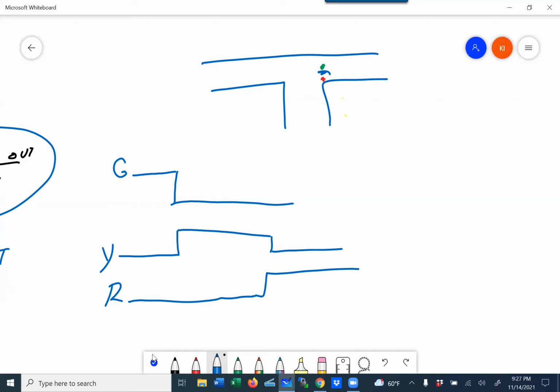So for each one of the lights, for each lane, when you're building the line, remember, earlier, you had a circuit in lab 3 or whatever, where it gives you the priority, and then you would have 3 lines coming on. You would have a green, you will have a west green, a south green, and an east green, basically lights that would start to come up, okay? So now you can't use that because in your previous case, when green went away, red immediately came on. You can't do that anymore. You want a delay in there.